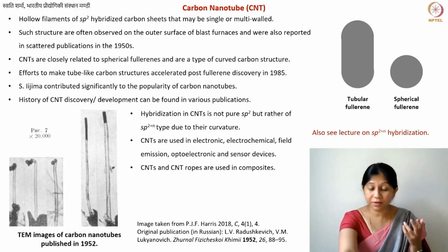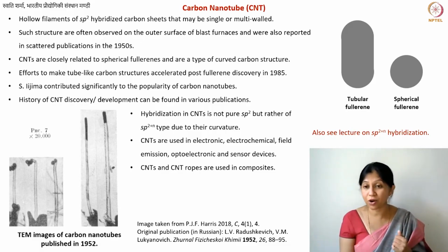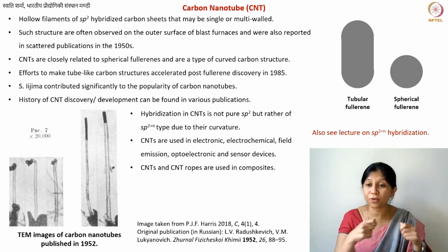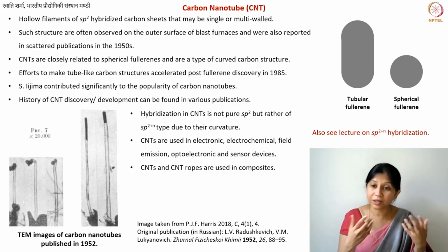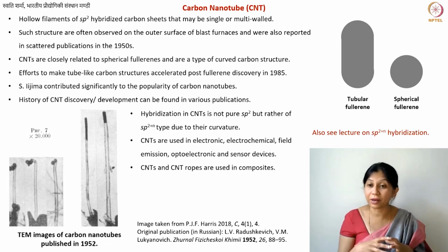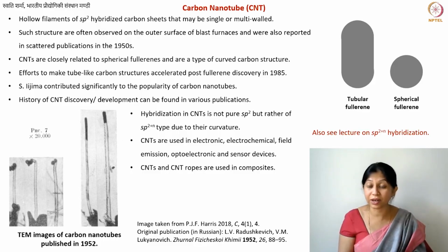Okay, because of the mechanical strength of the carbon nanotubes, whether it is validated experimentally or not, the point is that carbon nanotubes are already extensively used in composite materials. So you can add tubes directly, like what we did with the short fibers, or you can also make ropes of carbon nanotubes. Now you have strands. And with the strands, you can either braid the strands and then make these nice preforms, or you can directly add these strands inside your polymer matrix. So you can also make carbon-based composites. So carbon nanotube reinforced plastics. That's also a new and advanced area of research.